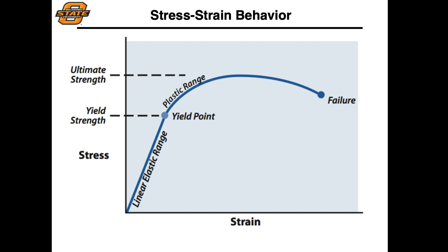Now, as you recall, in our traditional stress-strain behavior for materials, as we're deforming that material, increasing that strain, we'll have a linear region where our stress is increasing linearly with that strain or deformation until we get to some yield point, where we'll then experience a nonlinear plastic deformation regime until we get to the point where that structure fails.